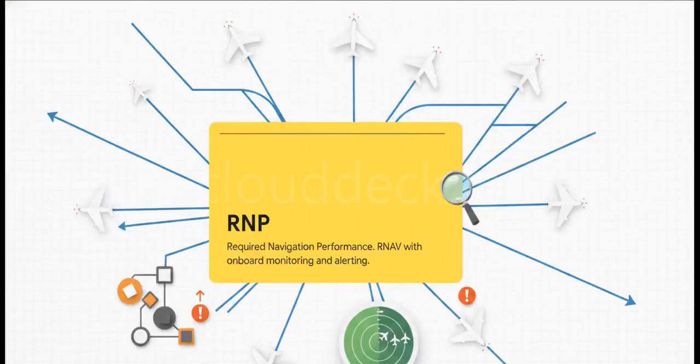Let's move on and see how this builds into something even safer: Required Navigation Performance, or RNP. RNP is essentially RNAV, but significantly upgraded. The key difference here is that an RNP system includes internal onboard performance monitoring and alerting, something like RAIM, or Receiver Autonomous Integrity Monitoring. Basically, if the navigation signal degrades or loses its integrity for any reason, the RNP system instantly alerts the flight crew. This guarantees they never unknowingly drift off their intended course.